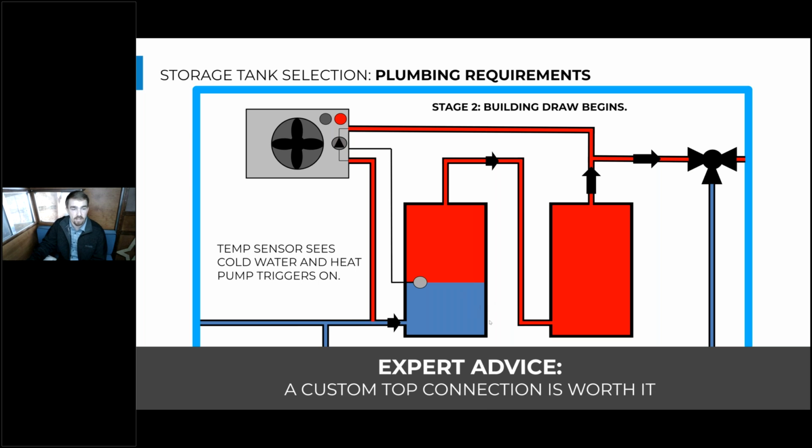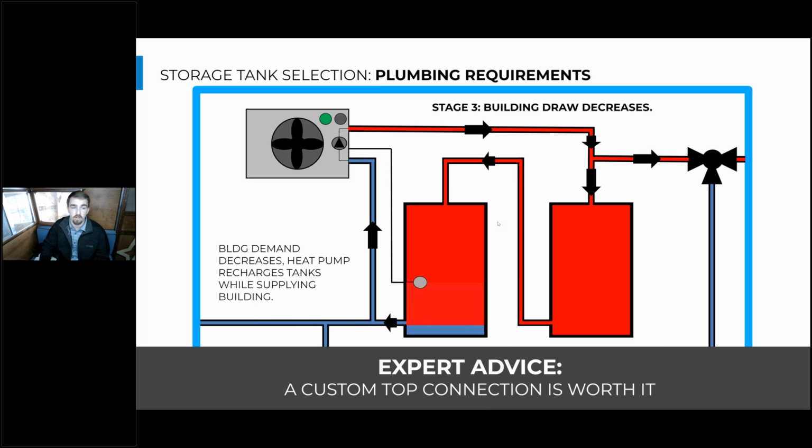But at a high level, as soon as all this cold water fills the bottom of the tank and the cold water reaches this sensor, that's when the heat pump will turn on and either try to supply the building with hot water or recharge the storage. In this situation, you saw the storage continue to get cold, and that's because everyone has turned their showers on at the same time, and the storage is providing more hot water than the heat pump can make up. So that storage continues to go cold.